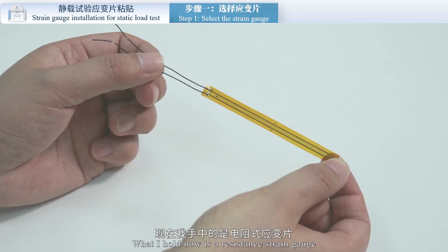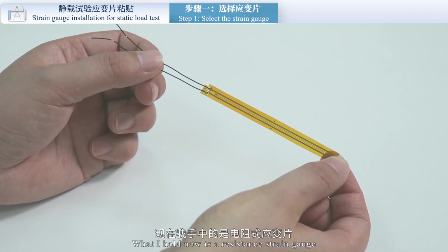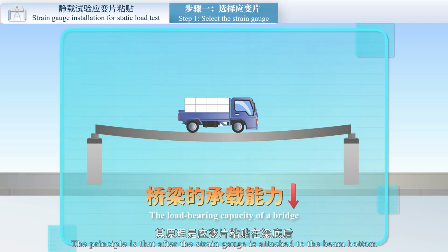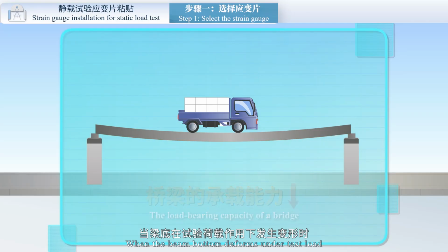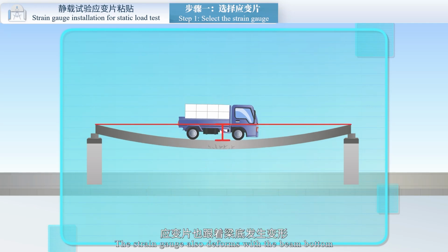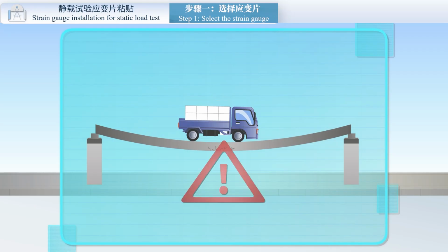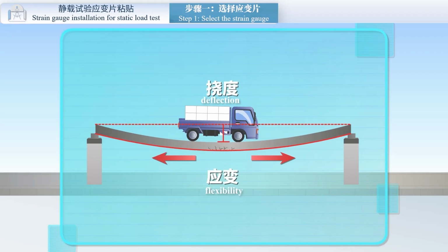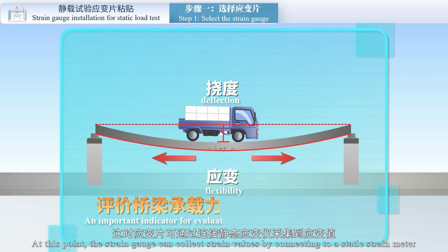What I hold now is a resistance strain gauge. The principle is that after the strain gauge is attached to the beam bottom, when the beam bottom deforms under test load, the strain gauge also deforms with the beam bottom, thereby causing changes in the strain gauge's resistance. At this point, the strain gauge can collect strain values by connecting to a static strain meter.